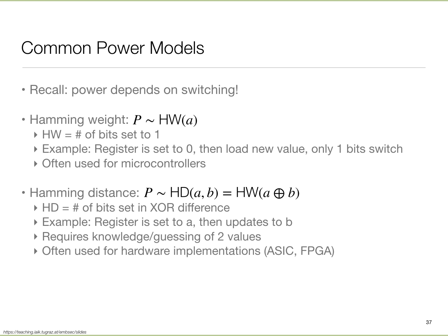Okay, so let's imagine it has a power supply and I'm allowed to put my power meter there. Okay. Say it again. To the power supply, you add random power noise. Yeah, but how do you do it? So the problem with adding noise to the power supply proposal is that you have to be careful that you're not adding noise into your circuit, because then the circuit will suffer, right?